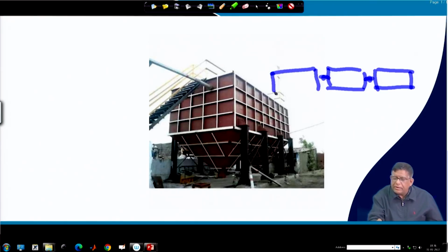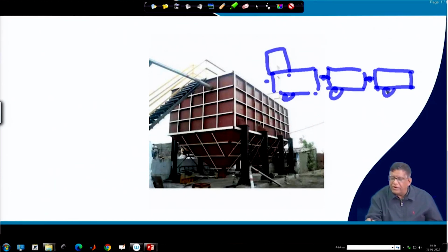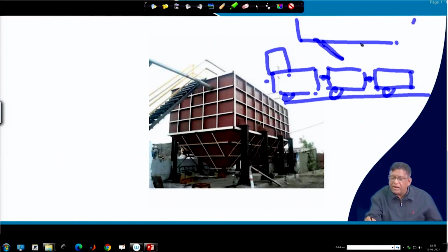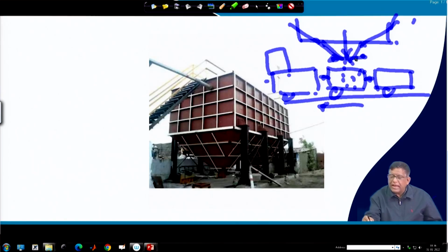Suppose this is your locomotive and they are just going over this track. Now, this bunker is over here, and it has its upper portion here. So now this bunker unloading is taking place. This gate will start falling, and material will start coming over here. As soon as the wagon advances in this direction, this gate gets closed, and again it goes up, the next wagon comes over here, material starts to flow, and it goes.